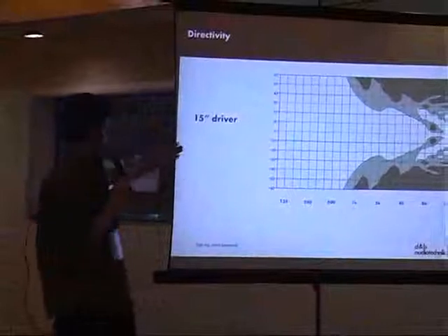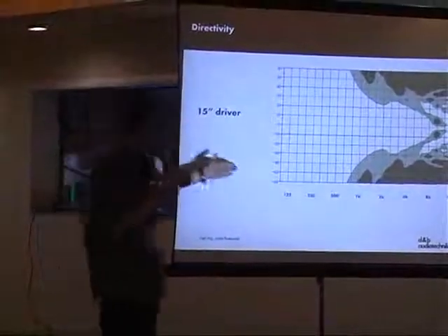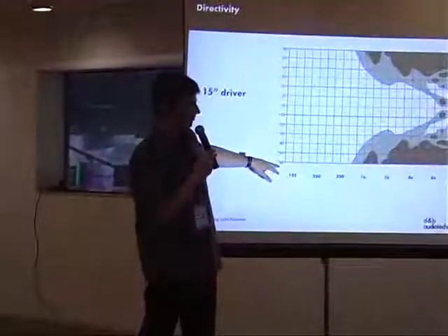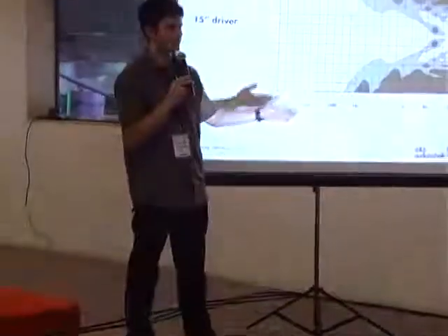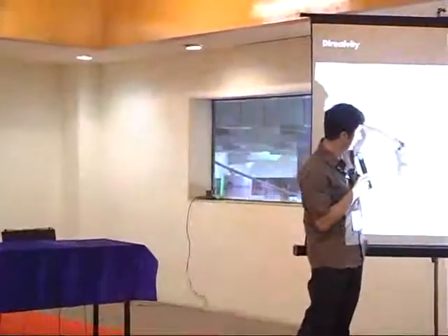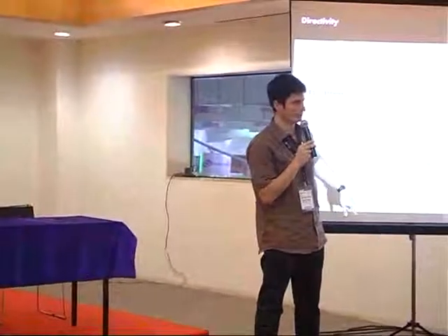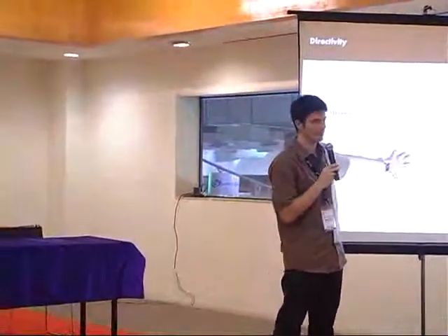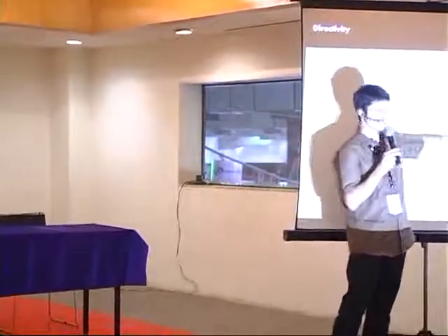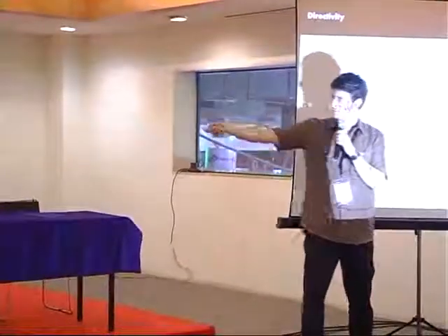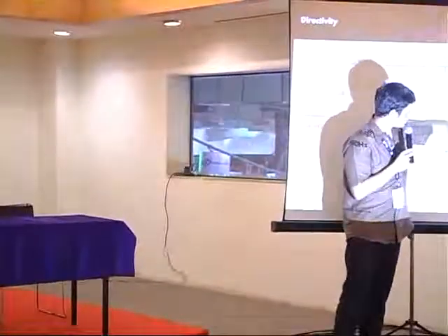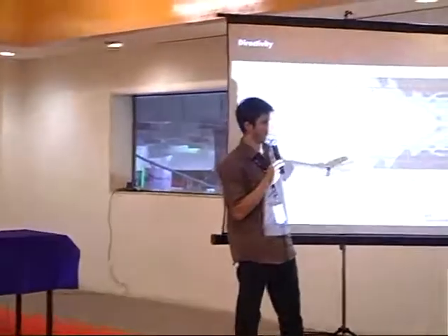And this is of a 15-inch driver, and we can see, well, obviously for lower frequencies, at least when we look at the range of plus minus 60 or 120 degrees in total, it doesn't even seem to drop by 6 dB if we wander outside of the main axis by 60 degrees. So you clearly see it's pretty much omnidirectional down here, and once you cross into the mid and high range, it becomes directional all of a sudden. And it even seems to become more directional the higher the frequency goes.